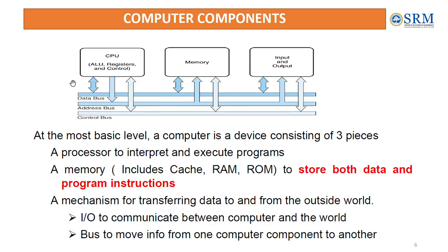Now you can see that the CPU is standalone, and memory and I/O devices are standalone. To communicate the CPU with the external world like memory or I/Os, it has to communicate through a physical medium. That physical on-chip medium is the buses. Usually there are three buses: data bus, address bus, and control bus. The control bus carries various control signals.